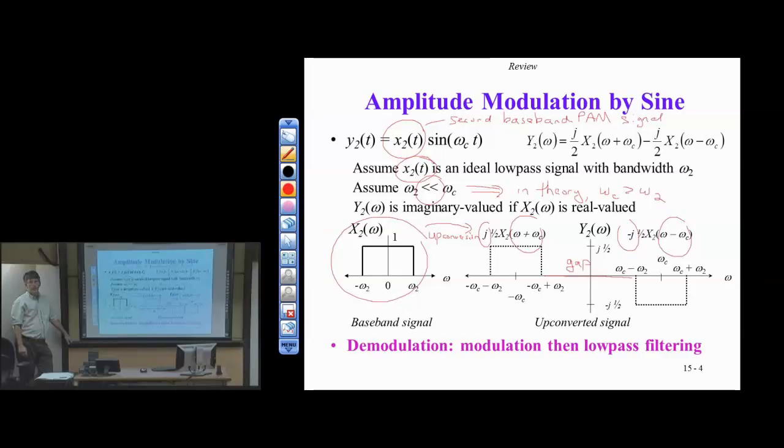90 degrees. So we want to keep the sine wave we're using 90 degrees out of phase of whatever we're using for the cosine. We'll talk about that in the block diagram coming up. On the transmitter side, it's easy enough to do this. This is lab 2, generating cosines and sines. We can be pretty accurate on the transmitter side to keep these 90 degrees out of phase, with look-up tables, difference equations, whatever we want to do to implement the cosine and sine. But on the receiver side, we want to do our phase-lock loop so that we keep these 90 degrees out of phase.